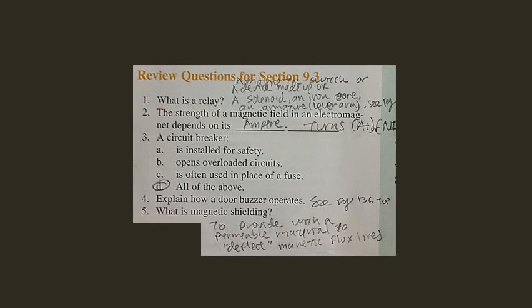This once again energizes the coil and opens the contacts. This action continues on and on as long as the voltage is applied. The device buzzes due to the vibration of the armature. An extension may be placed on the vibrating armature to which the striker is attached. The striker hits a bell. This is the principle of a doorbell.